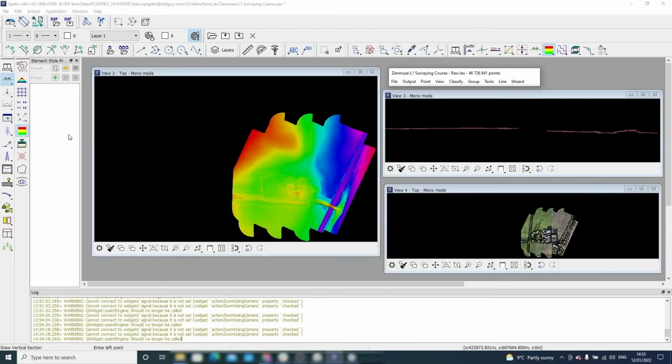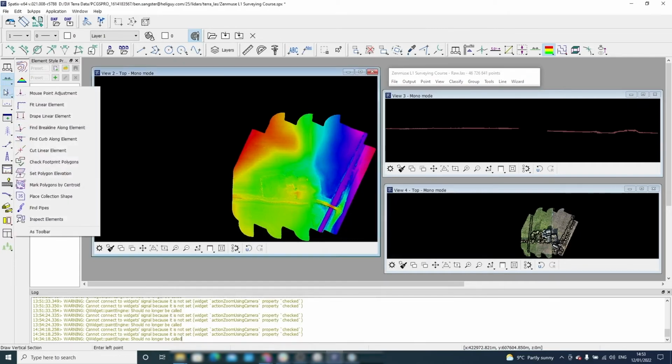We have just completed the check ground step with the support of our DTM. In the final part of this section, we can return to the Processing Wizard and classify the above ground features and the height from the ground. We also want to copy our results back to the inactive points and noise points, as we no longer require a thin dataset. This ensures most of the points in the dataset are assigned to a point class.